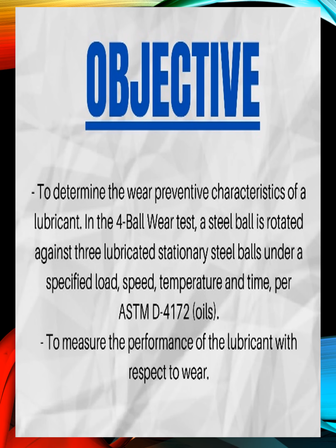As we know, all lubricants and lubrication technology are essential in reducing friction and wear losses in a machine. The key ingredient of the frictional system is a lubricant, for example grease, oil and solid lubricant. The 4-ball tester, also known as the Shell 4-ball tester, is used to characterize lubricant properties such as wear prevention, extreme pressure and friction behavior.